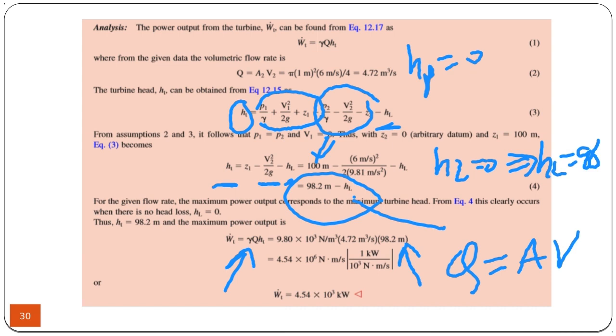So it would use up some of the available power from this 4.5 megawatts. So instead of 4.5 megawatts, it will produce, let's say, 3.8 megawatts, and 3.8 megawatts is the mechanical output of the turbine, but it's going to rotate a generator, and that generator might have some efficiency, like 95%. Generators have high efficiencies. At the end, your available power would be something like 3.5 megawatts.